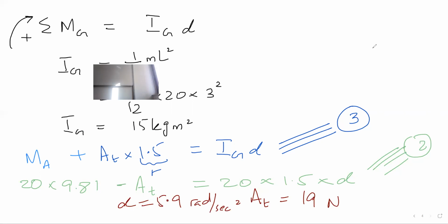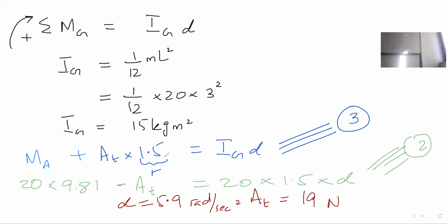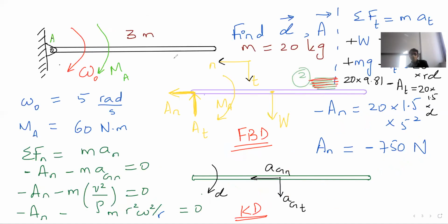First, why didn't we multiply the first part with R, 1.5? We did AO into 1.5. This one? Yes. That's a moment, not a force. Summation of this capital MA is the moment that is given to me. Newton meter. 60 Newton meter. So 60 Newton meter plus force multiplied by distance, Newton meter, equal to Ig alpha. Newton meter. This is moment.